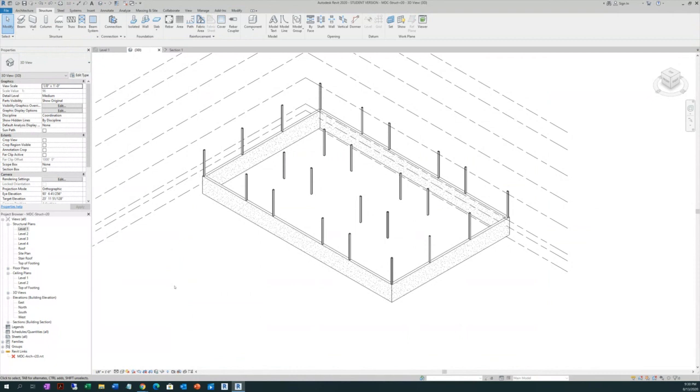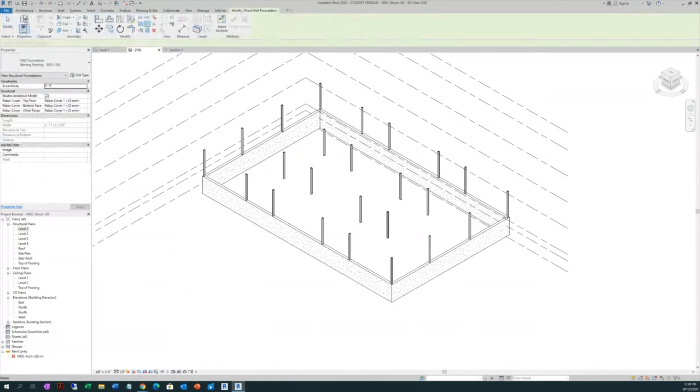Now you can do it the same way, with structural, the whole foundation of the bearing footing. Make sure it's going to be 36 by 12. Then I hover over that and press tab on my keyboard and place it in one shot. You can do it on the floor plan or you can do it like that in one shot.